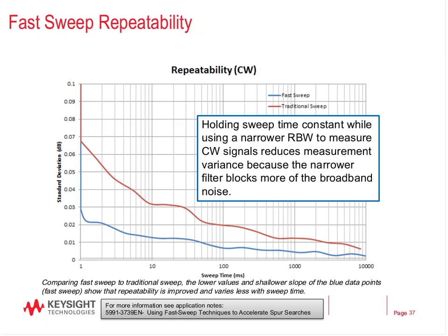Not only that, because you have the added flexibility now to improve your time, you can actually improve repeatability. So going back to your uncertainty budget, if you can improve the repeatability of your test, that might actually deliver a higher yield. So if you hold the sweep time constant while using, for example, a narrow res bandwidth filter, because maybe sweep time is not a concern. Maybe you want to keep the sweep time about the same, but you want to narrow the res bandwidth filter. By narrowing the res bandwidth filter, you effectively are increasing the signal to noise ratio of your measurement. And if you're increasing the signal to noise ratio, what ends up happening is you increase the stability of the measurement. And so what we're showing here is you can actually get a much higher degree of repeatability if you hold sweep time constant and reduce your res bandwidth filter. Okay, and the good news is you don't have to take a hit in sweep time. In most cases, it'll be either faster or the same with a higher degree of repeatability, or vice versa. You can flip it.